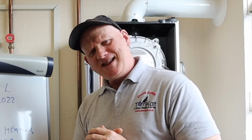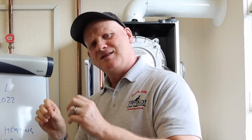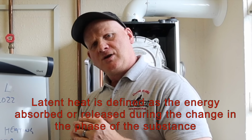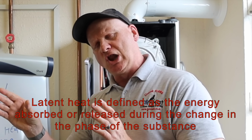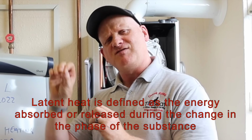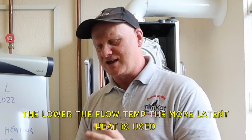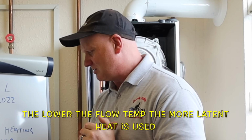Why do we call them condensing boilers? Well, we call them condensing boilers because they take a lot of heat out of the flue system. It's called the latent heat. So in a nutshell, what that means is our flue temperatures go lower than the dew point of the water, which is 55 degrees. So instead of it being steam coming out of your flue, it actually turns back into water and runs through the heat exchanger and then through to drain. So that's why they're called condensing boilers.